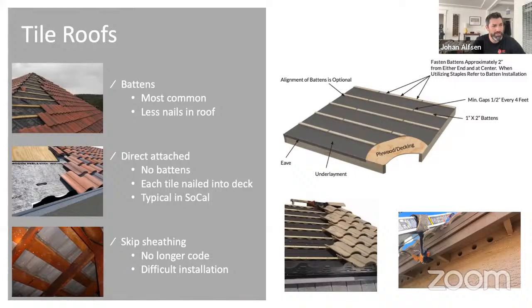If you look to the left, the way they're built up. Right now it's pretty standardized, where you've got your truss system, your rafters, then you have plywood or decking, and then you have some sort of underlayment, typically a 30-pound felt paper, or sometimes a synthetic underlayment. You can tell when it's synthetic when they have print on it and it says some type of manufacturer, maybe like a GAF or a CertainTeed or Grace. Sometimes it's a Grace Ice and Water Shield adhesive. For different kinds of climates like Florida, they'll sometimes require an adhered underlayment.